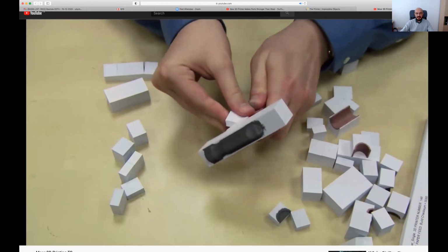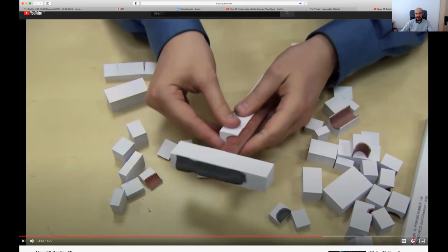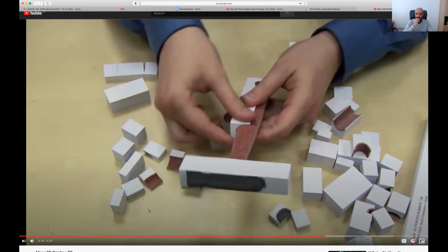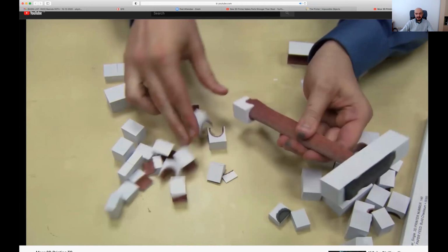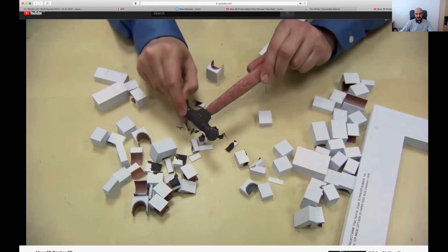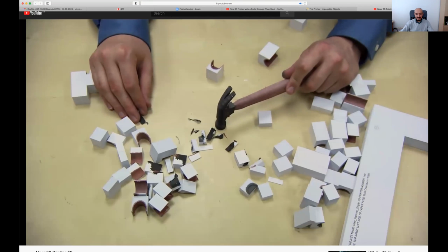The whole benefit of the SDL process becomes apparent when you actually try to remove the waste material from the finished object. Because we applied higher density adhesive for the part and lower density adhesive on the waste. So these are the cubes actually, and as we discussed, it's kind of a support structure. It means that the waste material comes off very easily. Also, to make it easier to remove the waste material is cut up into cubes, or as we call it, dicing, which means that the waste material can be removed very easily into nice little blocks. That means that you can get very intricate parts out of your model when it's finished.